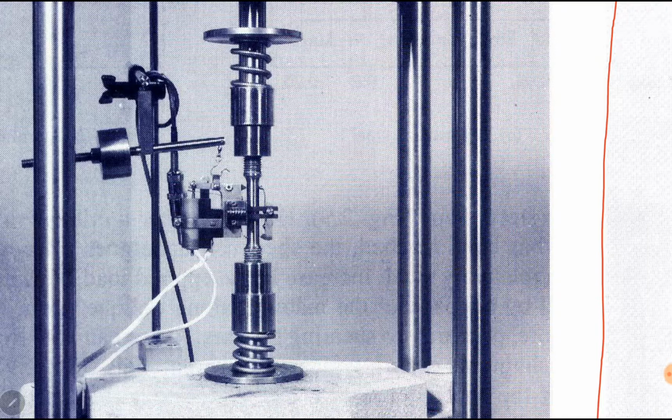First we have to find deformation in rod AB to find displacement of point B. Then deformation in rod CD to find displacement of point D. And from that we can geometrically calculate displacement of point E. So how we will do it? Rod AB is under compression. Cross-section area of the rod is already given. E of the rod is already given. Force has been calculated already, 60 kilonewton.